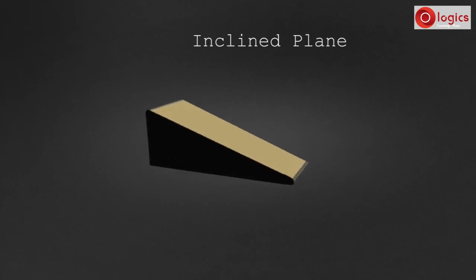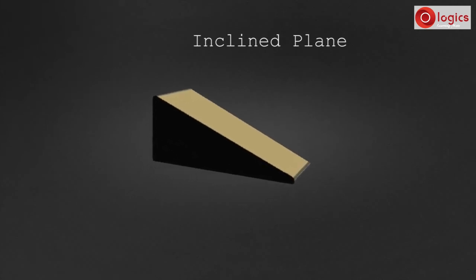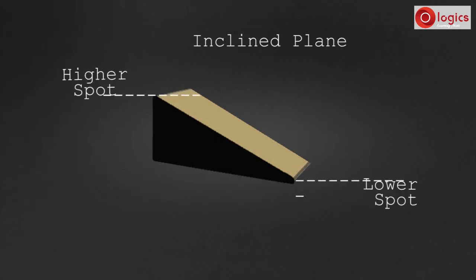Let's understand about inclined plane. An inclined plane is simply a sloping surface. It is used to make it easier to move a weight from a lower to a higher spot. Let us take an example. This is a weight of 100 kilograms. When you want to keep this on top, you need to apply high effort to lift in this direction. If you push this weight on the slope, you can bring this weight onto the top with less effort.